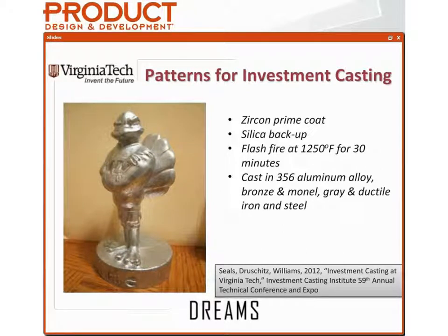And again, traditionally, this would have required us to CNC machine some type of master pattern out of a metal or some wood, perhaps. In this case, it's all been designed digitally. Actually, in this case, we started with a 3D scan of a 2-foot-tall statue, then reduced its size, and then printed it all within the span of about a day. And then we had our master pattern, and we're ready to start making our statuettes here.